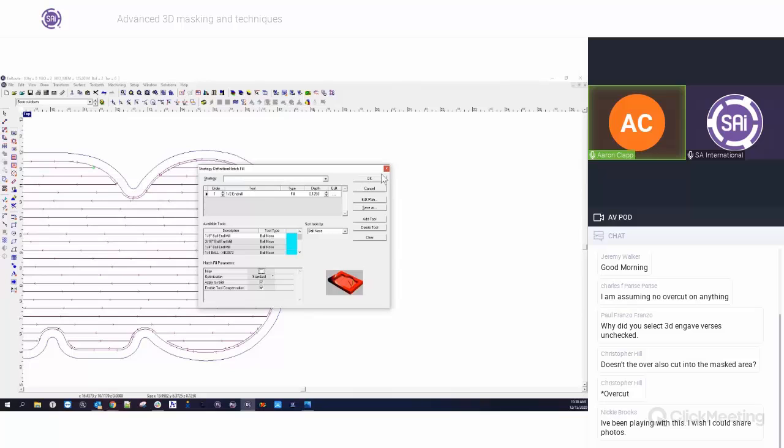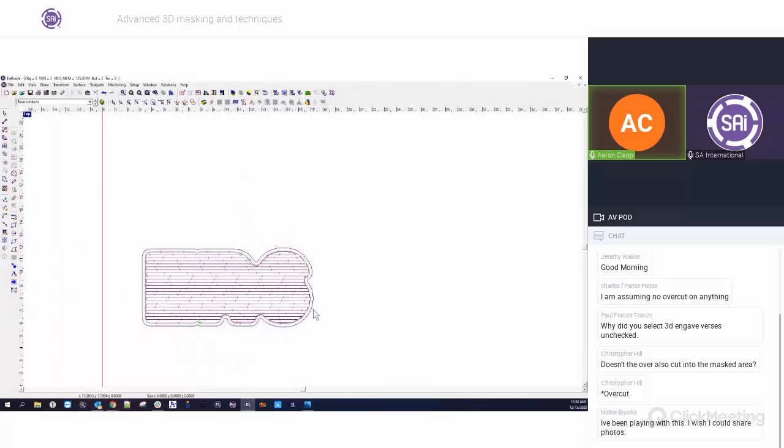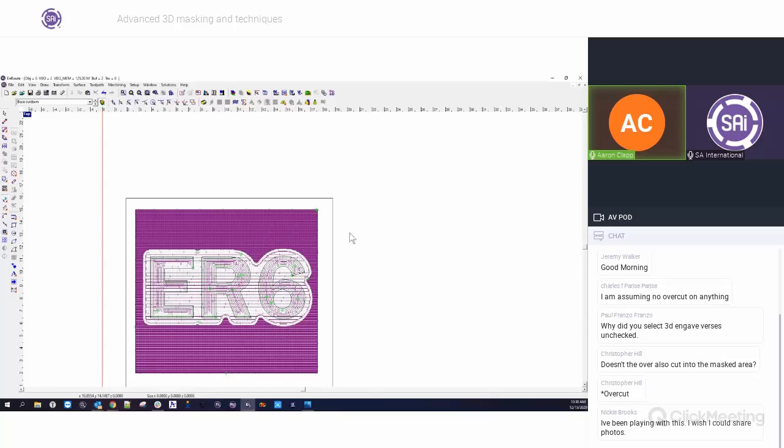When I went to cut it, I made it a little bit bigger so that the tool would overhang just slightly. So just be aware of that. If there's sections like this where you're applying 2D toolpaths and you want it to overhang a little bit, you'll have to just create an outline that's a little bit larger. But in the 3D part, that's a good place for me to actually apply that overcut.